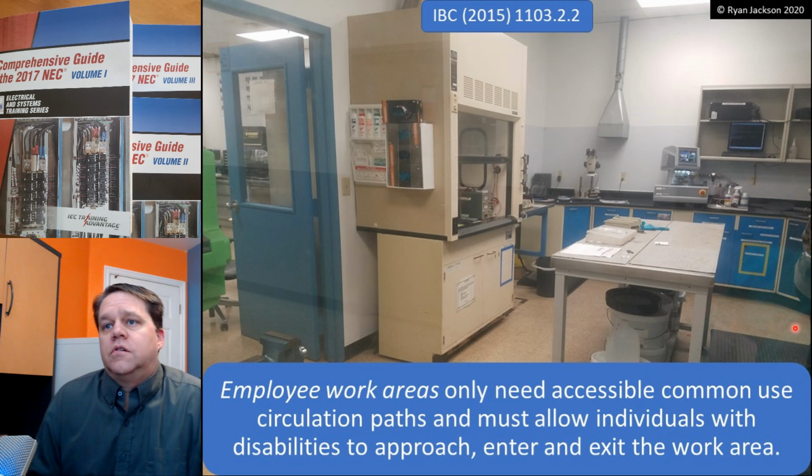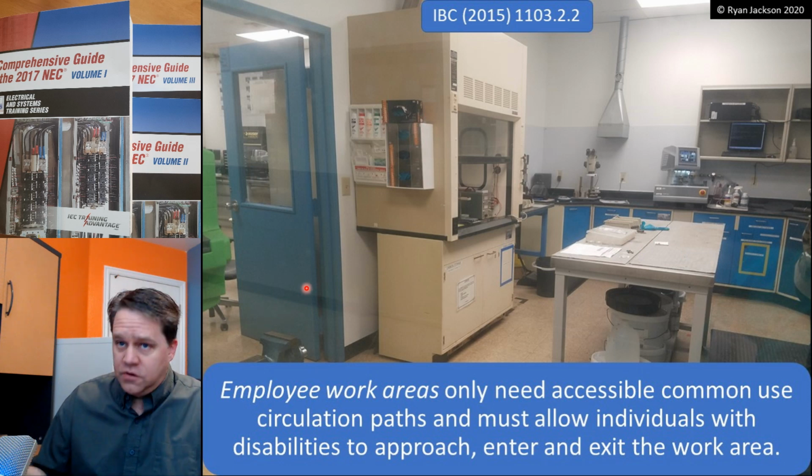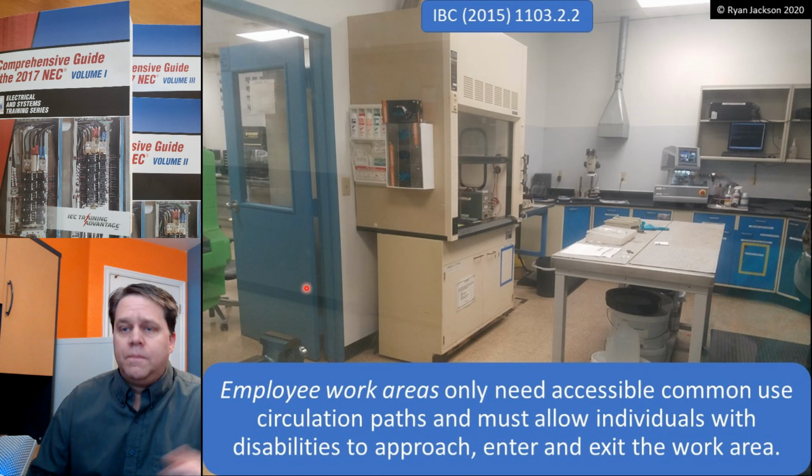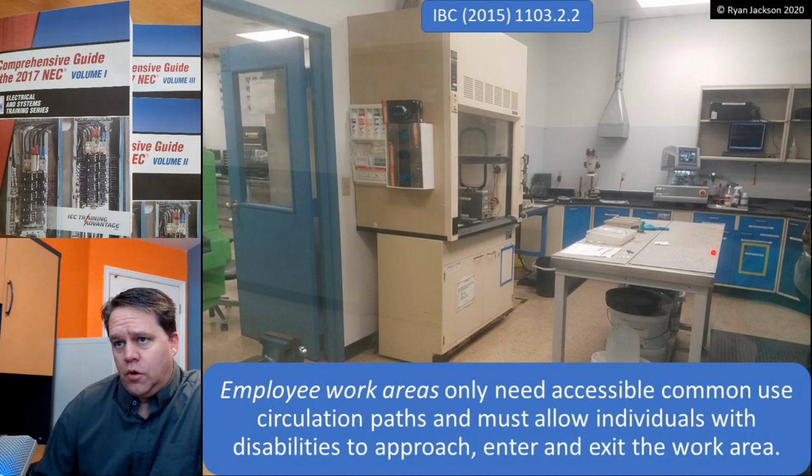So looking at this photograph here, this is an individual's work area. We've got a door here that has to be accessible. So I need to have at least a 32-inch wide door, a 3-foot door, and I have to allow people to enter and exit and approach the workspace. As far as the height of devices, the graspability of equipment, that's not regulated here in the employee work area.